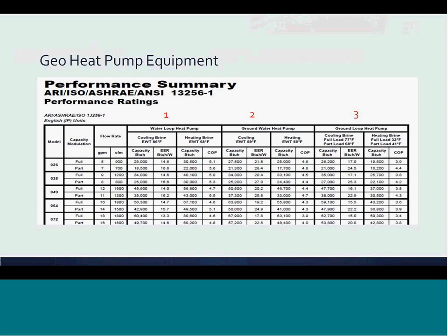When we rate water-to-air geo heat pumps, we don't use the same testing standard as air source heat pumps. This is frustrating to engineers and to contractors alike because we like to be able to provide a comparison of different HVAC system types to our clients. The approach outlined in the previous slide is a way to break down the system performance by outside air temperature for air source equipment and entering water temperatures for the water source equipment, so two dissimilar types of systems may be compared for the same project.